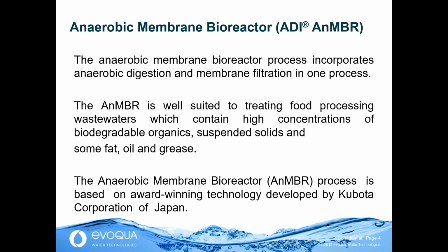So a little bit about the anaerobic MBR. As Andrew showed in his presentation, the anaerobic MBR is a process that incorporates anaerobic digestion and membrane filtration all in one process. The anaerobic MBR is well suited for treating food processing wastewaters, which contain high concentrations of biodegradable organics, suspended solids, and some fat, oil, and grease.